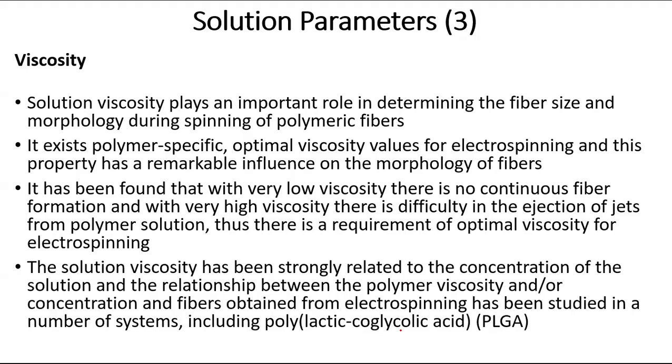If you use a very low viscosity, then there is no continuation of the fiber. Therefore the beads may form. So the optimal viscosity needs to be maintained. The solution viscosity is strongly related to the concentration of the solution, so it's the same observation that we can give for the viscosity as for the concentration.